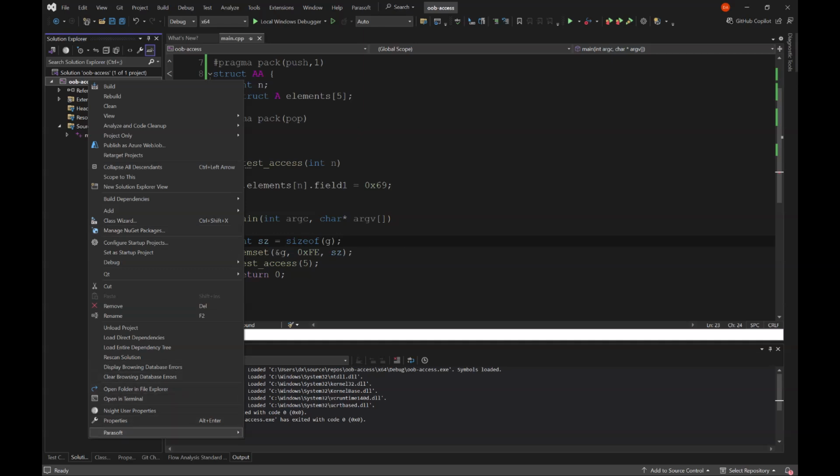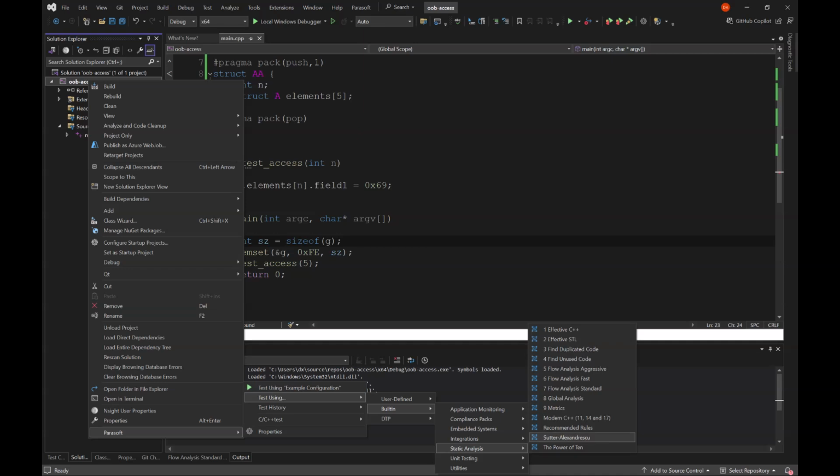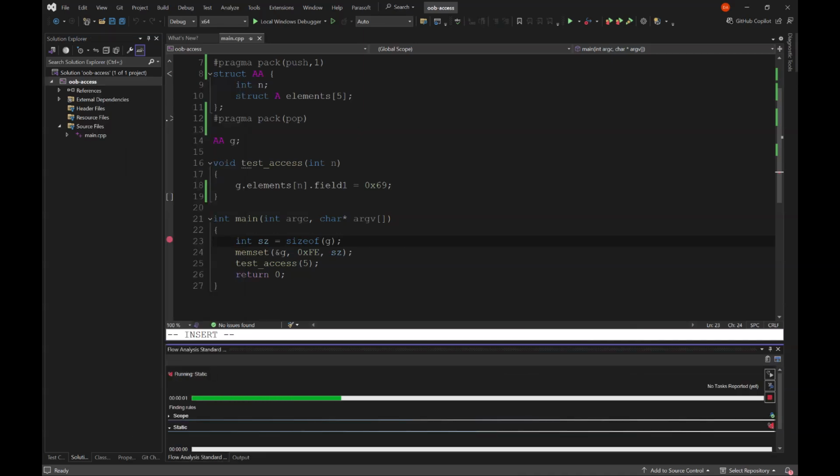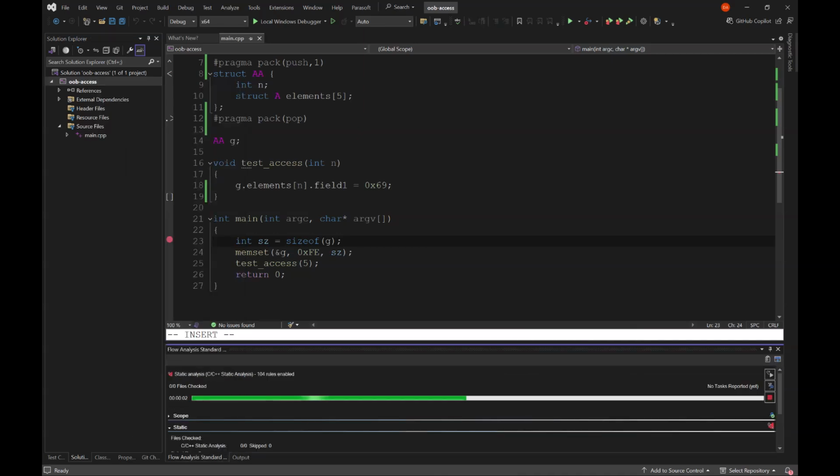After this correction, using the pragma extension, let us run again the static analyzer using Parasoft to ask if indeed there's an out-of-bound access in this piece of code now. Parasoft does not report an out-of-bound access when nothing is really out of bound. But if there's an out-of-bound as what the compiler is saying, then Parasoft will report it.